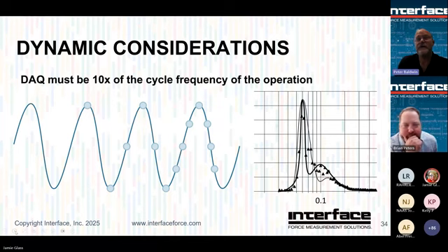Well, as you look at a sinusoid on the left, if I just take two samples, it just so happens in the diagram to show peak and valley, but the chances of actually capturing that peak and valley when we're only running at twice the operating speed of the load cell is very minute. Okay, so what if we choose 4 times on the DAC of whatever the operating frequency is of the load cell? Well, again, it doesn't really equate to replicating the waveform.